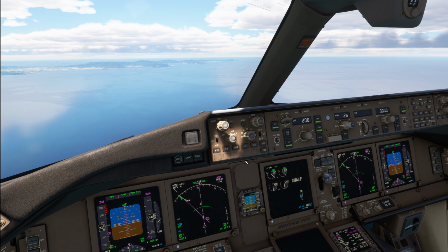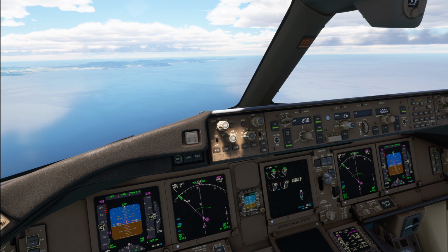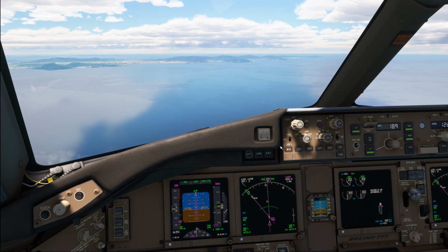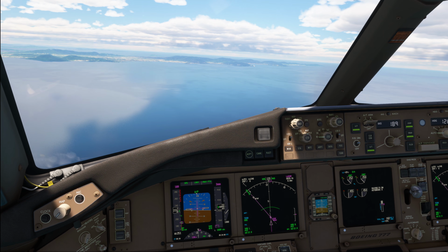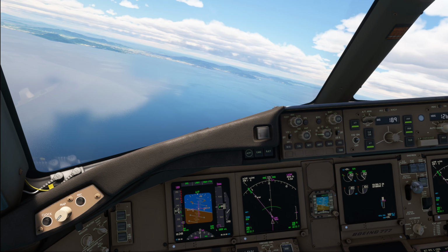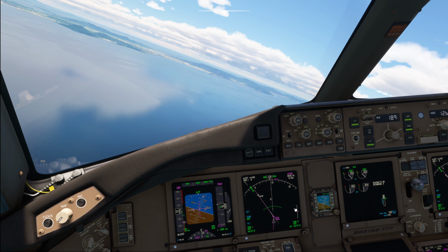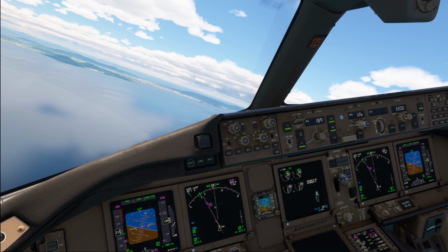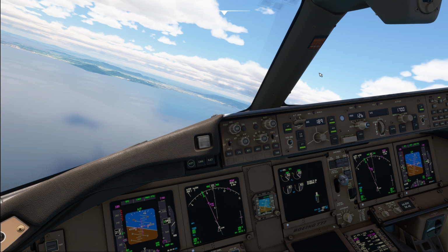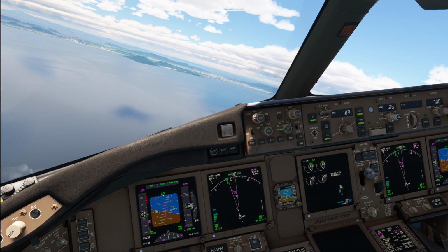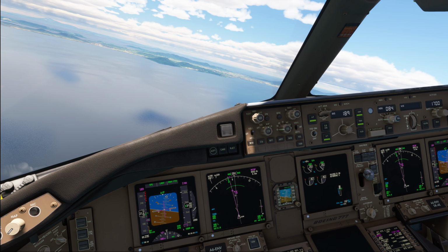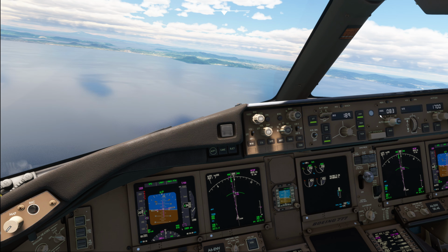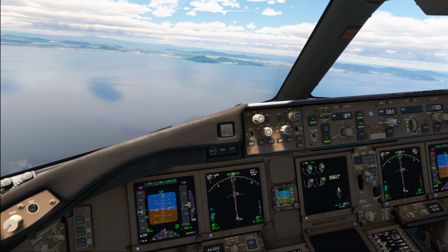Okay, let's get out the flaps into the 5 settings so that we can start reducing our speed further. And remember that we are going to follow our standard deceleration schedule. So let me get out a couple of speed brakes over here. Okay then, overflying Lazam, we can descend down to 1700, which is our final approach fixed altitude. Remember that on a non-ILS approach that is flown in LNAV, we don't have automatic setting of the runway heading, so we got to do that ourselves.